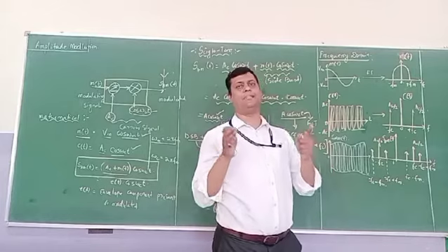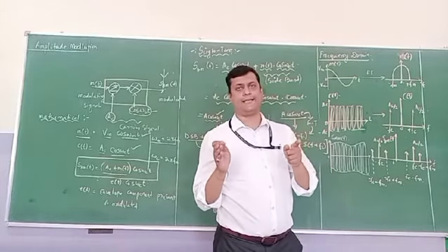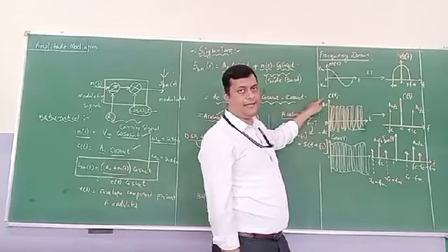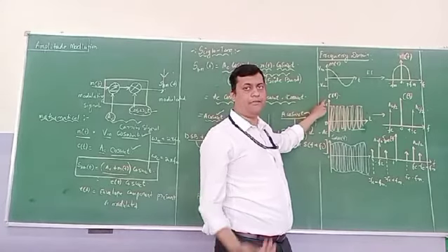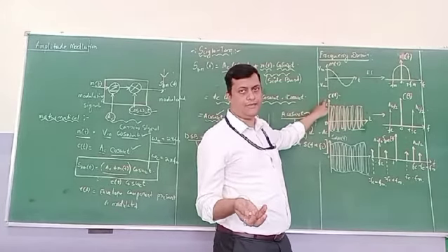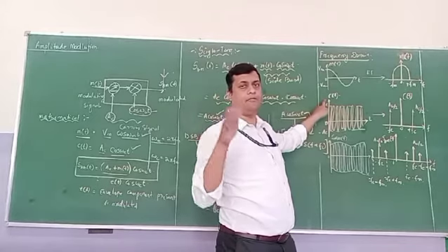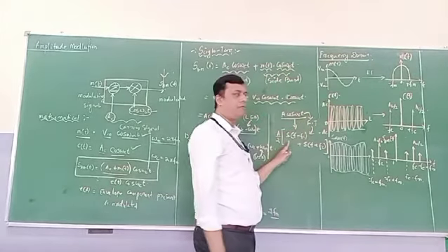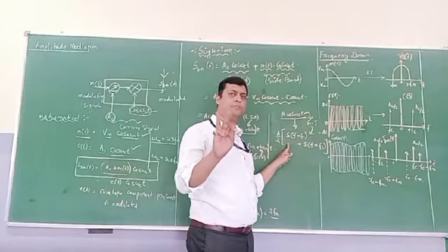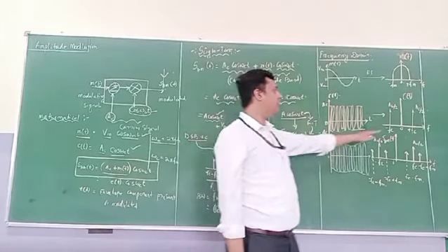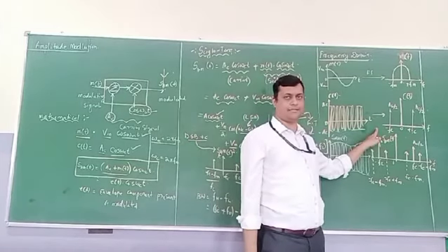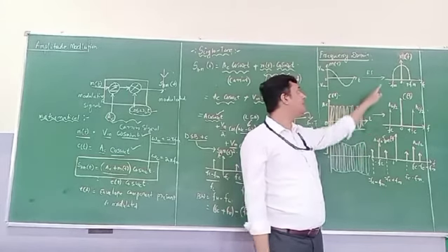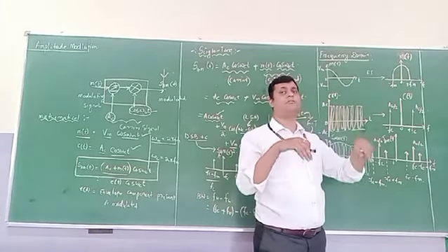But basically the bandwidth of modulating signal is fm. I will write all those things. Next, the carrier is a component which does not convey any sort of information, but it has a higher frequency with respect to the modulating signal. If you take a Fourier transform of a carrier component, you will get two spectral components, one at +fc, one at -fc. Done. Then when the modulating signal is obtained, this modulating signal is imposed on this carrier.